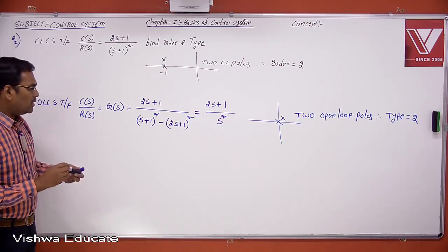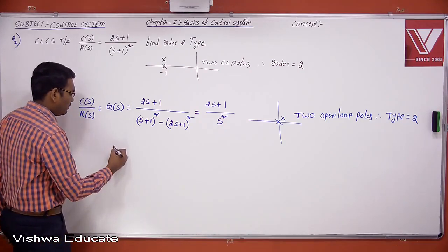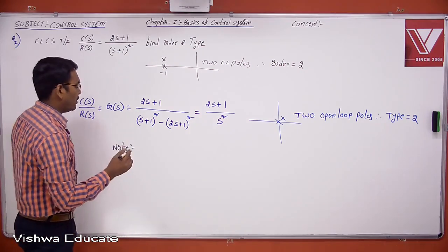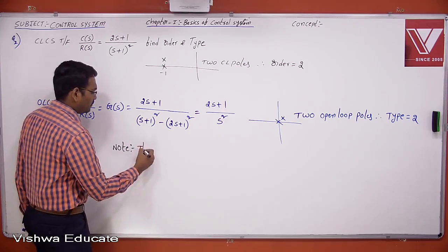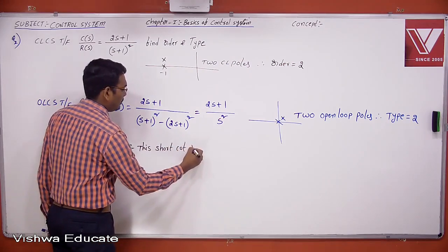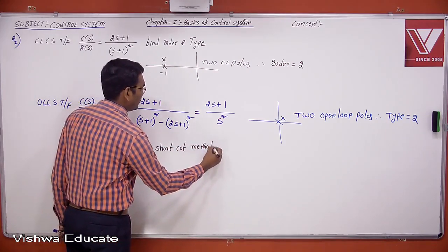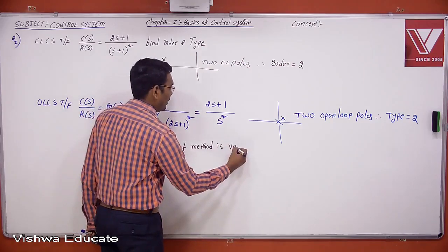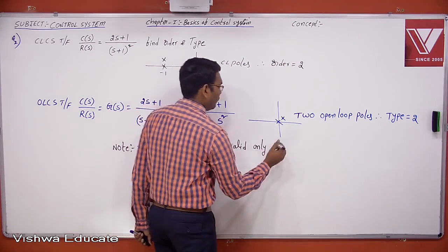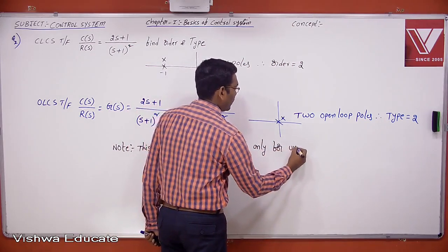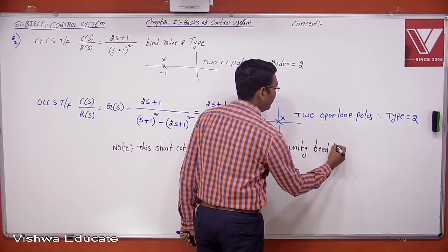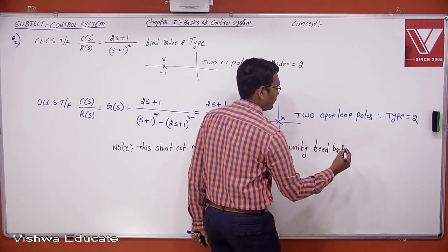Okay, and here you just take one note also, because you should remember this. Don't blindly solve from one question to another question. This shortcut method is valid only for unity feedback control systems.